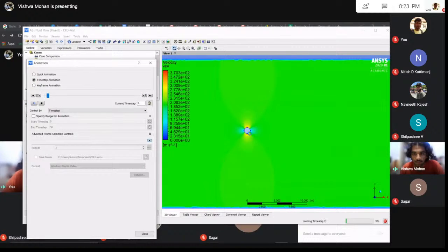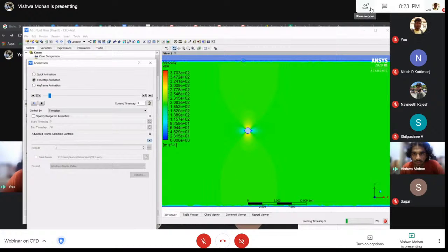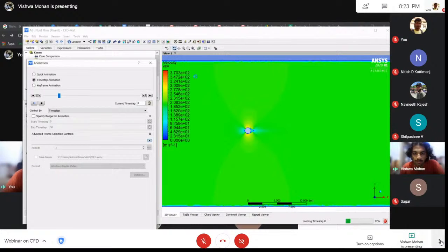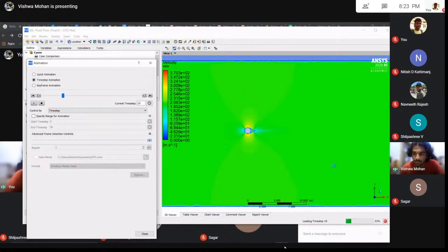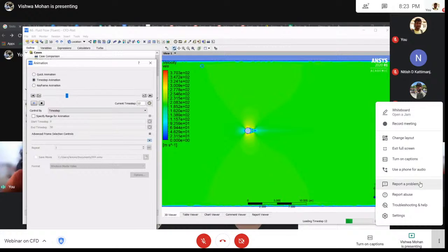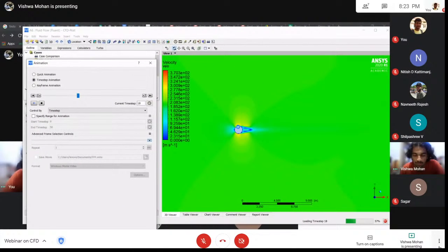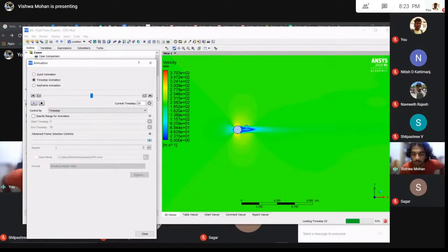So you see how the flow is developing. You can see over here, you can see on the walls. This blue part is 0 velocity, and all the other parts in the middle have different velocity. So you can see the domain is having certain velocity. Yeah, 200, and then this is at 0, and so you see some velocities being developed over here, and you can see some flow separation happening. This blue part, stationary fluid just leaving, and there is a tiny bit of fluctuation, and you see the point of stagnation over here, and you see that the fluid is speeded up over here.